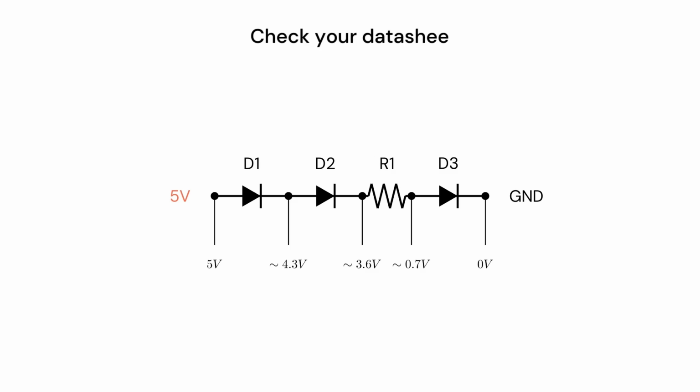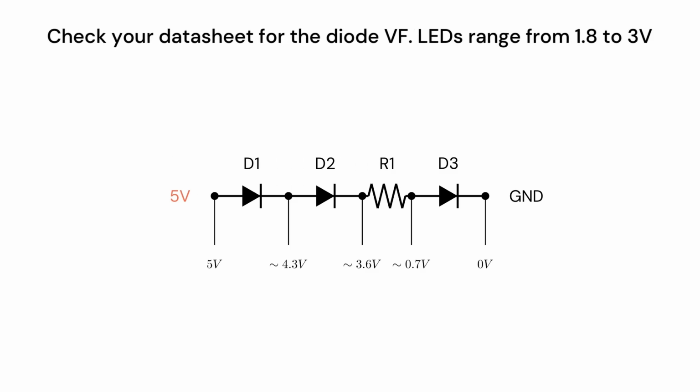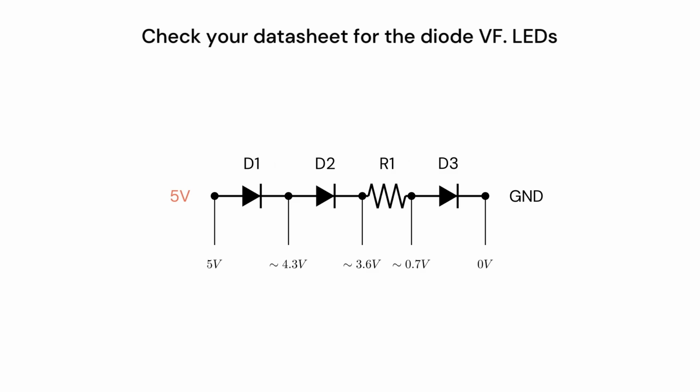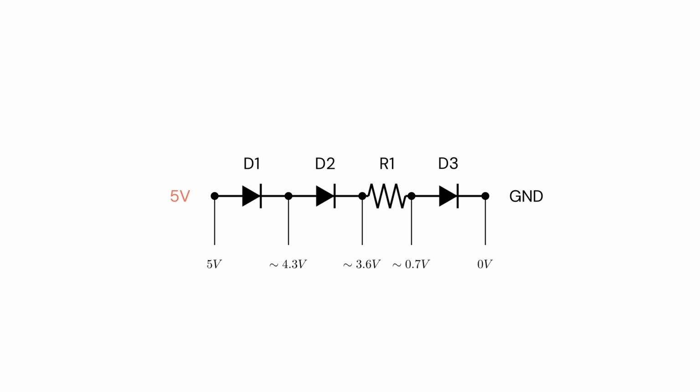After all, these numbers were not exact anyway, and the numbers all change if I switch to a different kind of diode, like a Schottky with a smaller voltage drop or an LED with a bigger one. So instead of counting volts, I count diode voltage drops using arrows pointing up or down. An up arrow means add the voltage equivalent to a drop. For example, the voltage at the anode of D3 is ground up arrow. And given that up arrows usually start counting from the ground, I can omit the ground, so I'll instead say that the voltage at this point is up arrow.